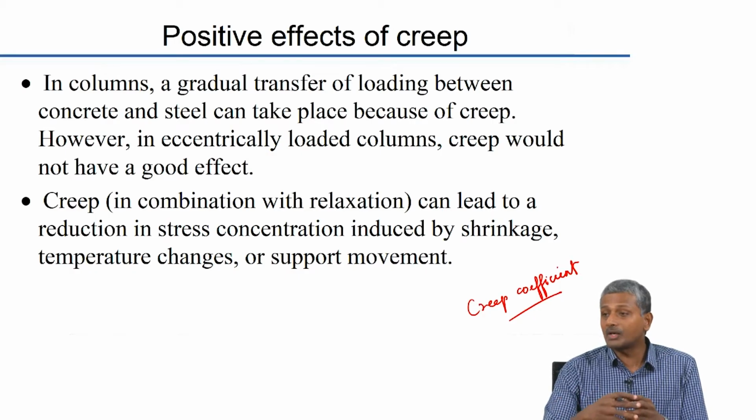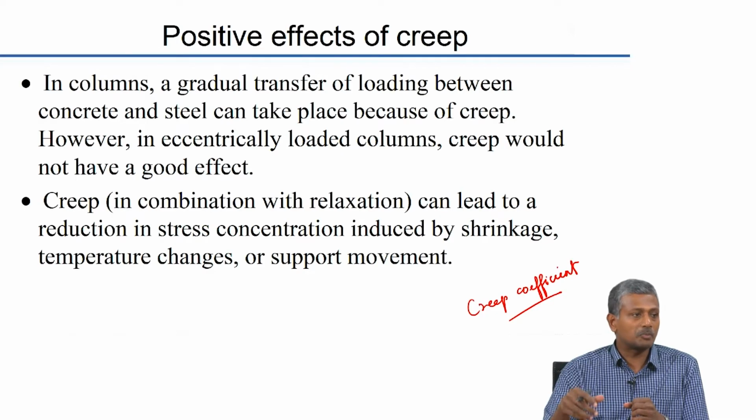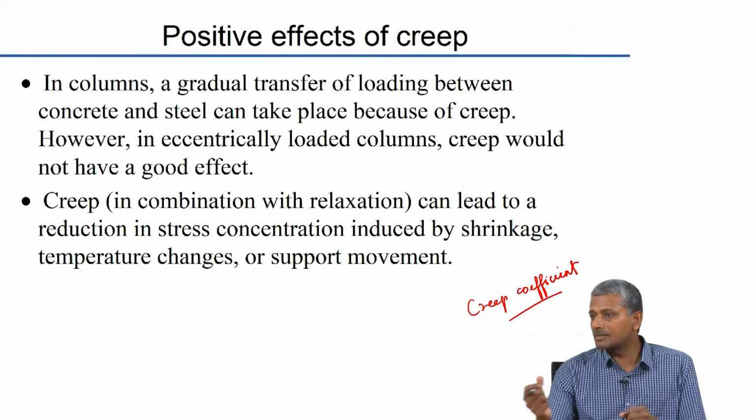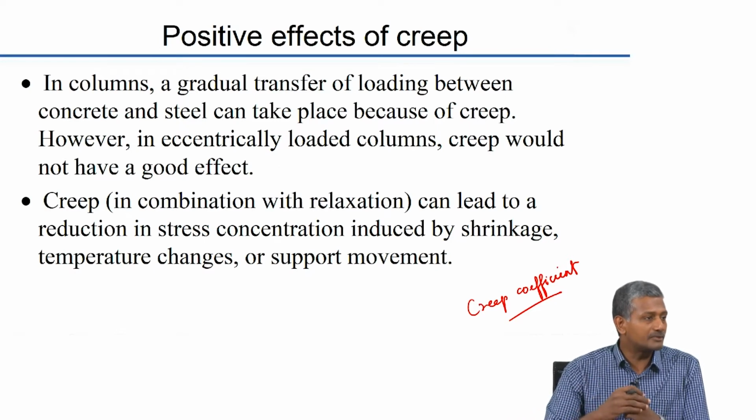However, what we are increasingly finding is that for the modern blends of concretes that we prepare these days with different mineral admixtures, different grades of concrete, sometimes incorporating very microfine additives, the creep coefficients that are existent in our present design codes are probably not accurate.